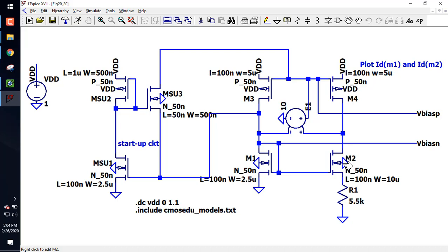So if I'm feeding back, because these two are the same transistors, and I move this up or down, I'm going to get a signal that goes through here and a signal that goes through here. Okay? Which one is going to have a larger impedance? This side, the signal going through, or this side? Yeah, this side, the one with the transistor and the resistor going to the drain.